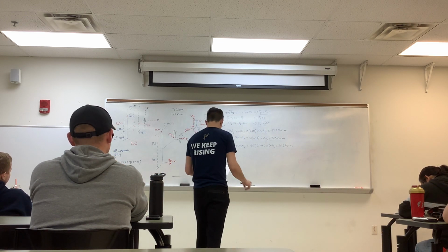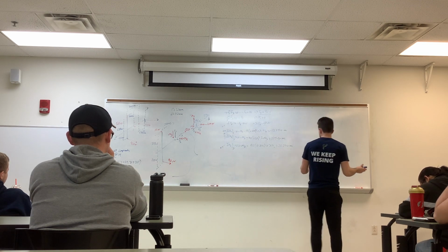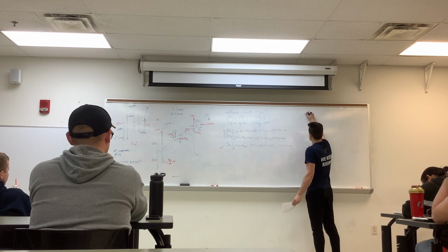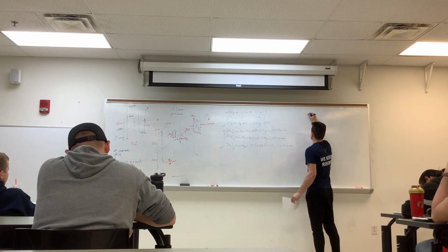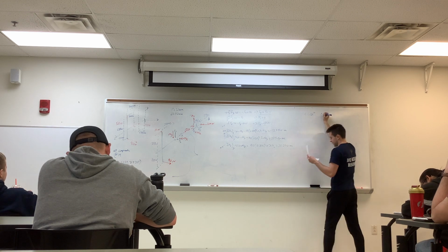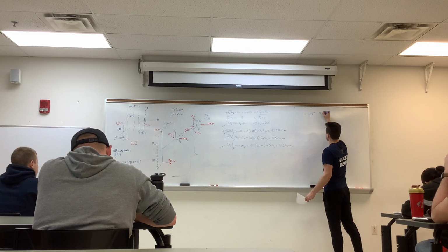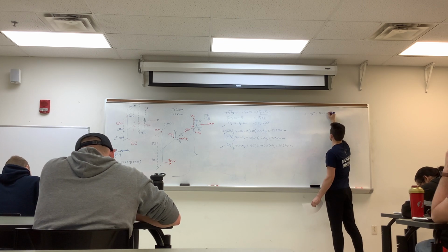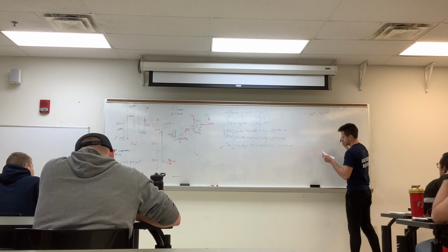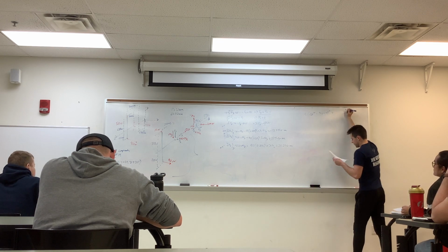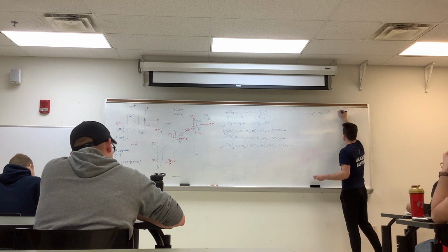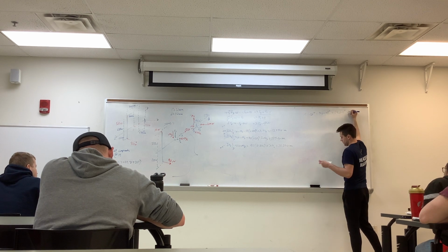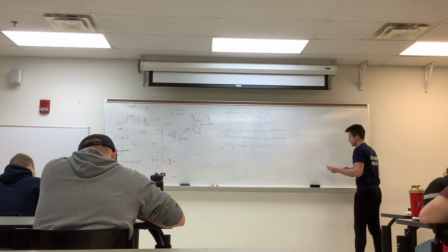I'm going to start with our stress. So I'm going to first find out area and then our I. So our area of the whole thing, which is just pi r squared, which we just have as pi multiplied by the radius, I'm converting this to meters here, 0.025 meters squared. We get our area to be 1.963 times 10 to the negative 3 meters squared.